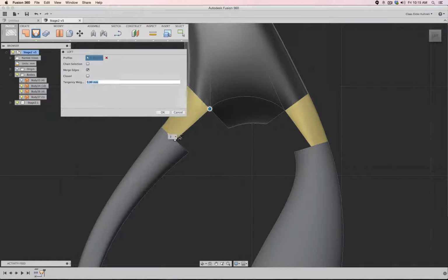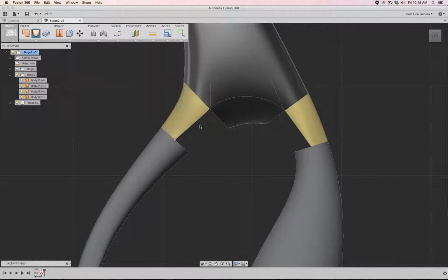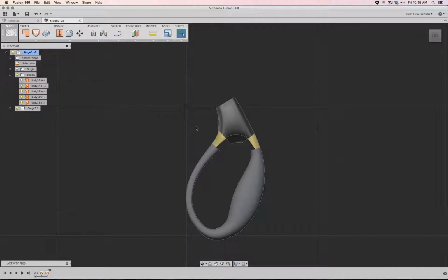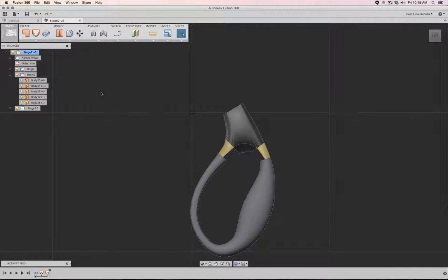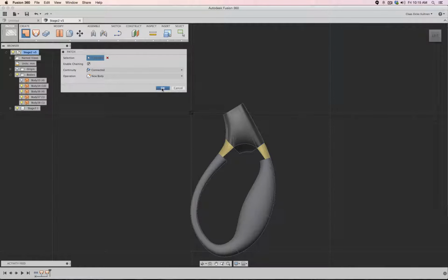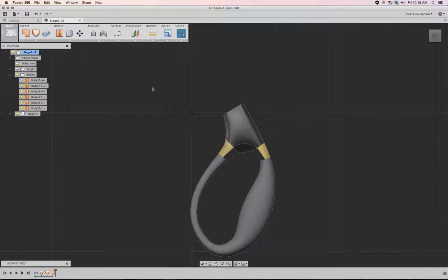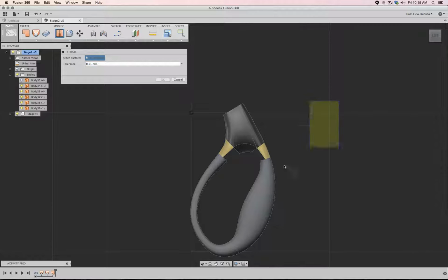So in tangent, profile 1 and tangent. Okay, good. So how does this actually look? Are these curves actually, is my T-spline built in a way so that the blend surface can create nice transitions? And currently it somewhat looks that way. So let's stitch this one together. Didn't I say stitch? Okay. Here, stitch.